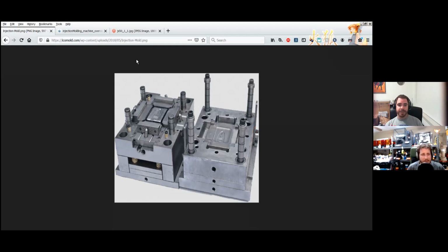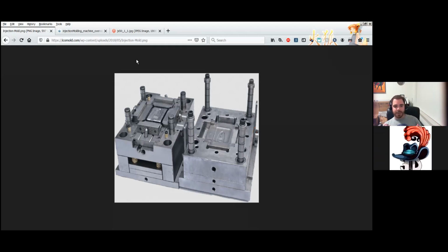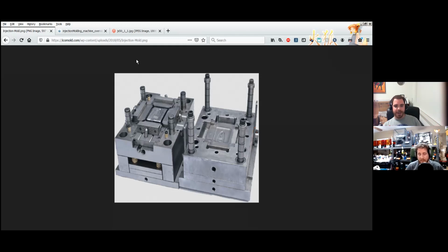You know? Right. And it just sort of speaks to the competing use cases for the two technologies, right? Yep. So with injection molding, you've got your high volume manufacturing where you want tens of thousands of something. But what you have to put into that is, as you were saying, the time and the money, and there's a lead time to that you can't get around. Whereas with 3D printing, you've got the agility to just change. Yeah, exactly. You just get as many as you need, no more, no less. You can adjust your design on the fly, and the next one you make will be different. Yep. Whereas you couldn't usually do that with an injection mold once it's finalized.